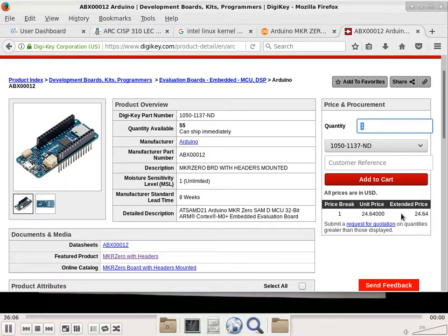But when you look at the components, it's not really that expensive. So you can actually put something together like that, in terms of having the components, and then you use the tool to program. So the Arduino tool is a C++ type of programming tool. And so it seems like, hey, I can do the same kind of programming as I can do on a PC. Well, not quite, because it doesn't have an operating system. It doesn't even have protected mode operation.